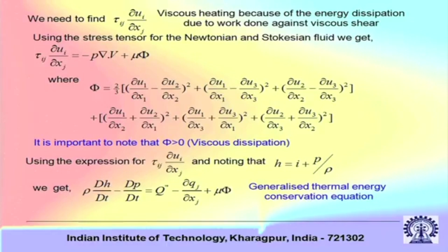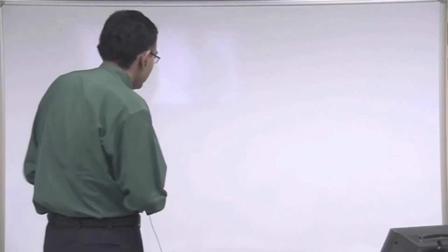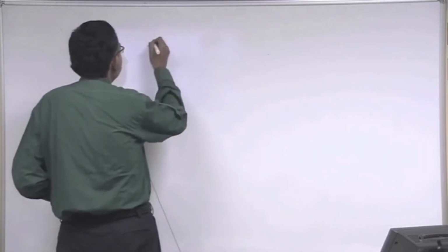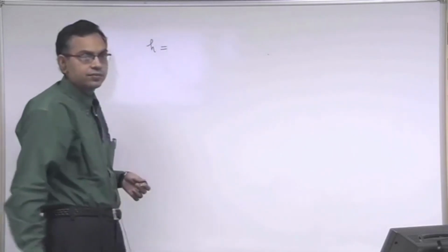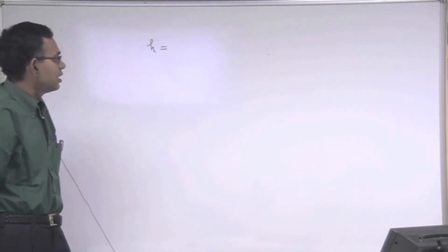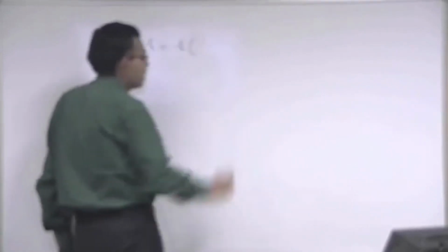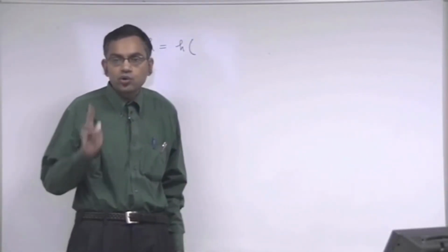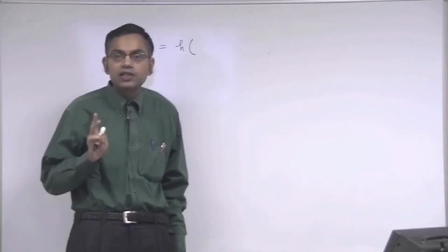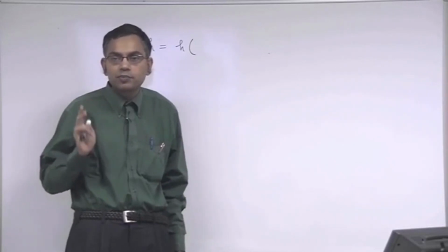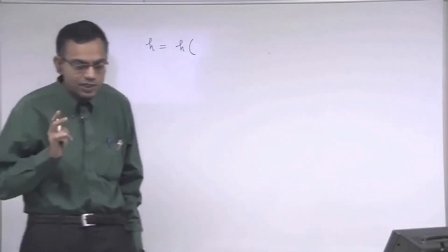Now, to do that we require certain thermodynamic basis. I presume that all of you have the thermodynamic basis, but we will discuss very briefly the concepts that we will be talking about as we go through the necessary steps. For example, H is the enthalpy. H is a function of what? H is a function of two independent intensive thermodynamic properties, provided the substance is a simple compressible pure substance.